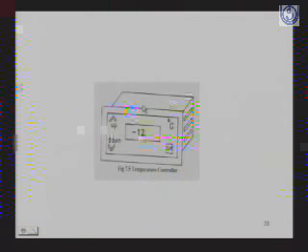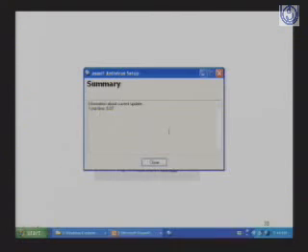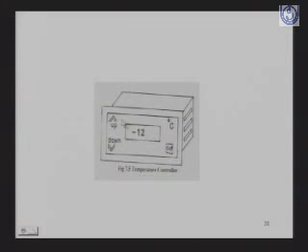And the third type is the temperature controller, which is based on the temperature setup. If the temperature is more, then this will sense it and act. If the temperature is less, then the flow of refrigerant will be more, and then the cooling effect will be more. These are the devices which we call control devices.